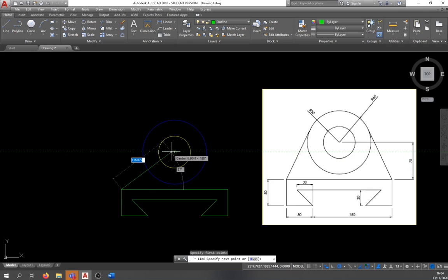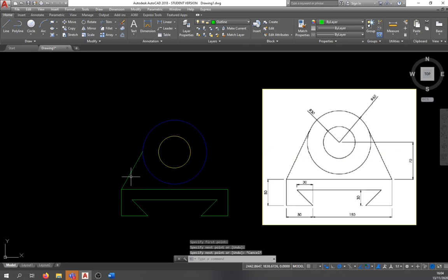So hover the mouse over the center point of the circle, and you'll see an object track line come across to get to the blue circle. Just click there, and to make sure it's the same on the other side, we can use the mirror command again. So click on mirror. I'll use the midpoint of this line as our mirror point, and then just bring the mouse downwards, click OK, erase source object, no, hit enter, and there we have our outline of the circle. I know it's slightly different there, but it's okay. I won't tell anyone if you won't.